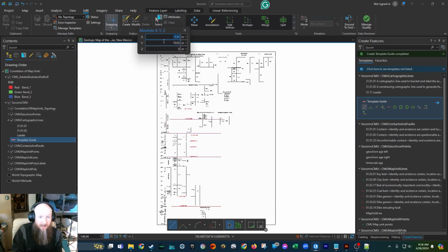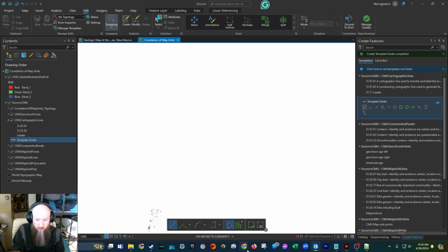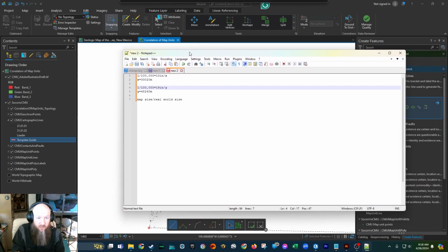So if I click on that, I can type in 0, 0, 0, because I set my units in my project options to be in meters. I physically put them at that location then. So if I hit enter, I now have a physical vertice at 0, 0, 0. And we know that we want to go vertically because we did the math to prove this. We know that we want to, again, consult our notebook. We want to go in the Y direction,